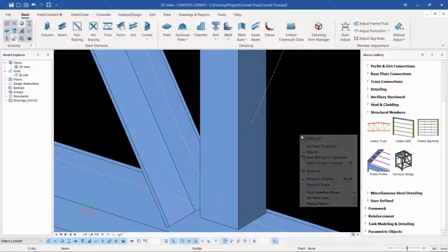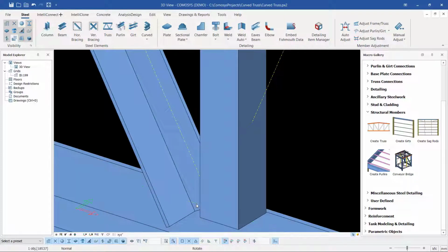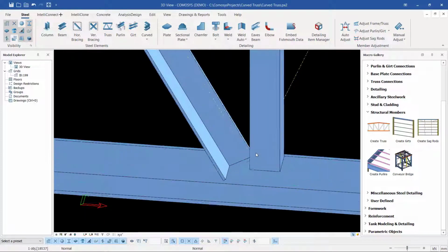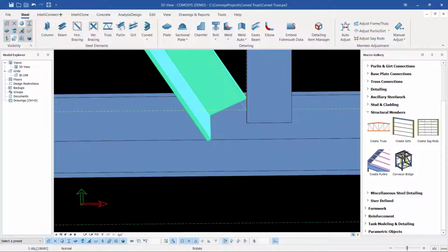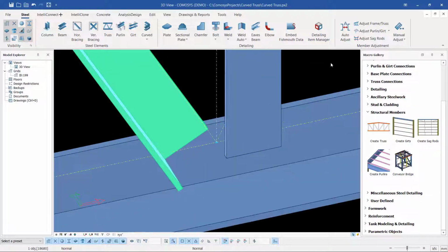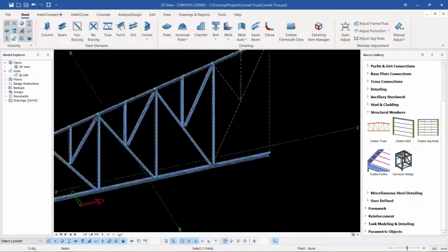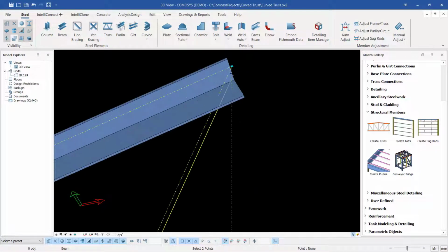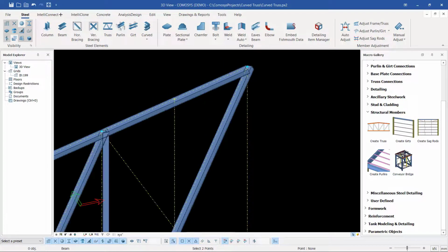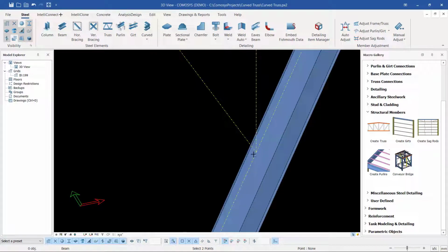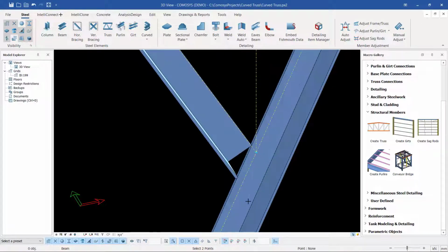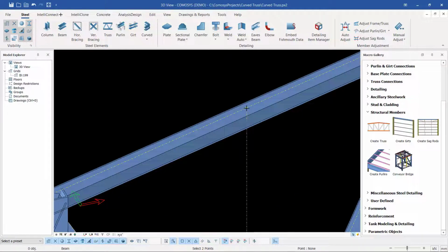So I'll turn this accurately. Let me turn that round so that I snap on that spot accurately. Let me select that member to show my point of interest so that I'll be able to rotate it accurately. So if I snap here, move all the way up here and terminate it right there, then I'll come to that spot and place another member here. Let me snap right there, then snap there, then add another one here.